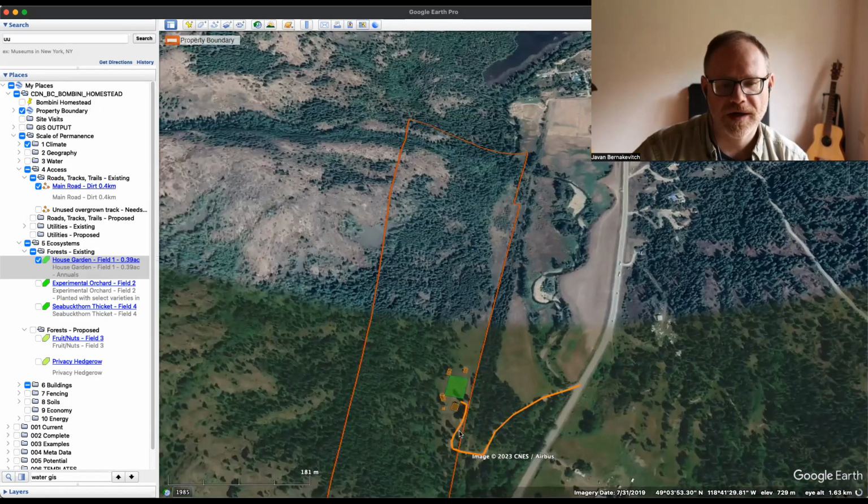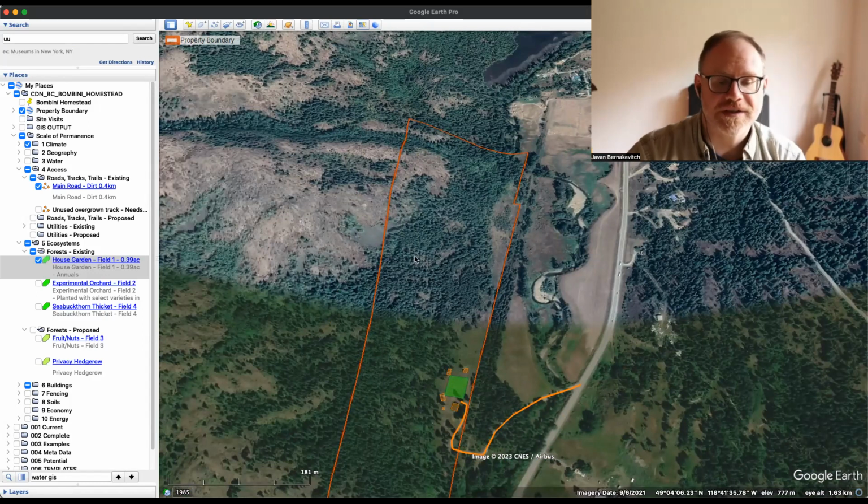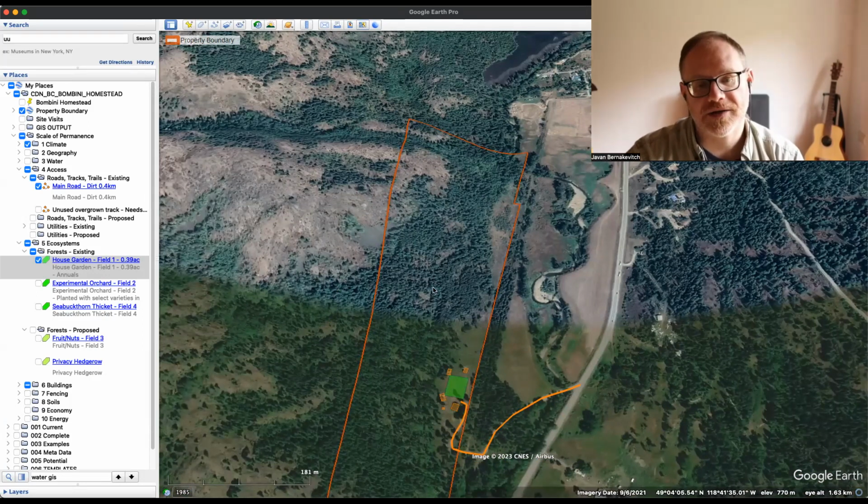Probably would have run the DJI Mavic 2 I had, and just over this area, because the problem with drones and photogrammetry mapping is that it only works on open canopy. And the nice thing about if I had done this, which I didn't have to do, is that it would have given me the detailed information I needed just for the site. But because this other area is so much difference in elevation, then that 30-meter pixel would have been enough.